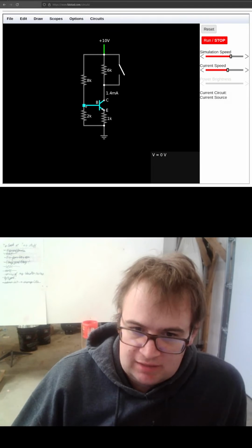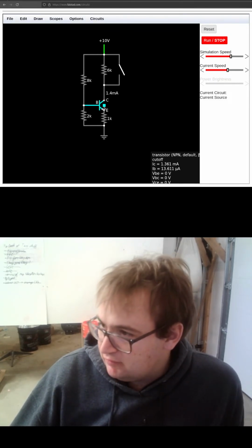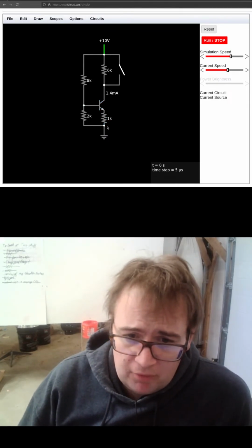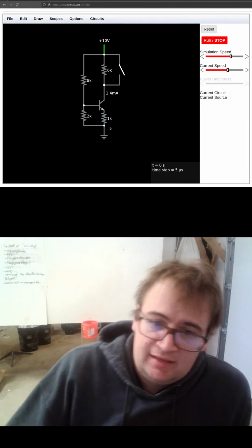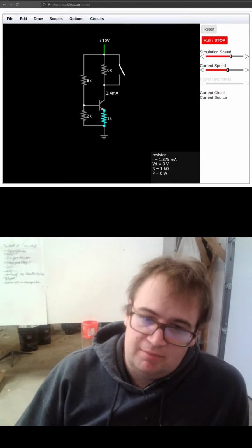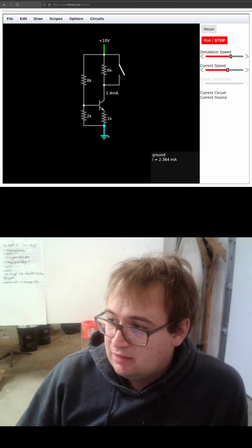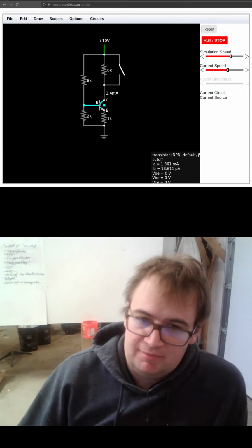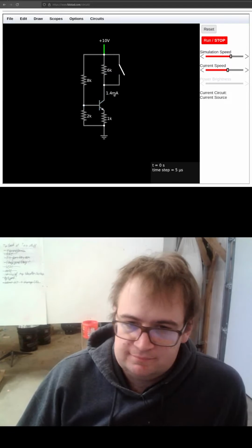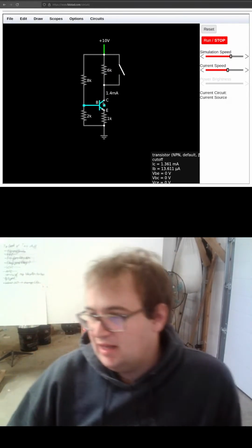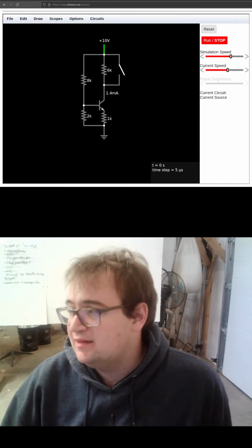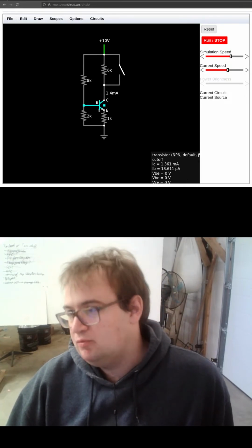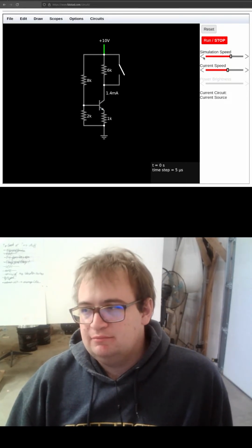So that means we have 2 volts here. 2 volts minus 0.7 volts. That is 1.3 volts. 1.3 volts. And we got a 1K resistor. Well, that means there will be about 1.3 milliamps going through here. That means that there will be about 1.3 milliamps coming this way. Now there it says 1.4 milliamps, so I would have to assume that means they are taking a diode drop to be 0.6 volts, which some people do.